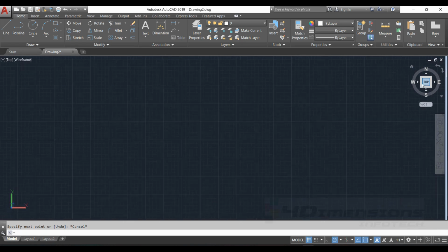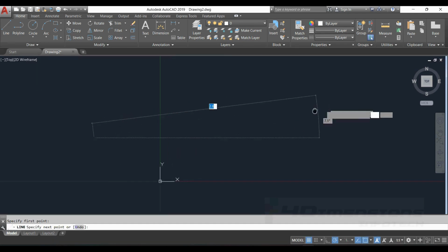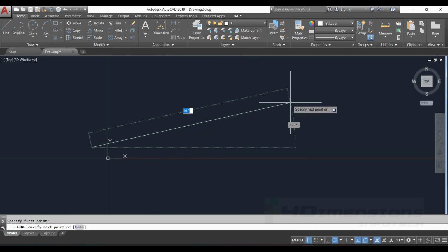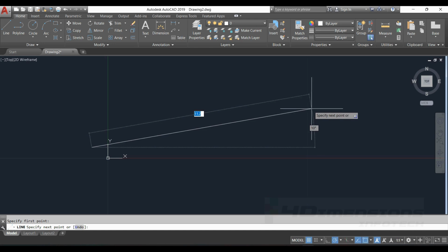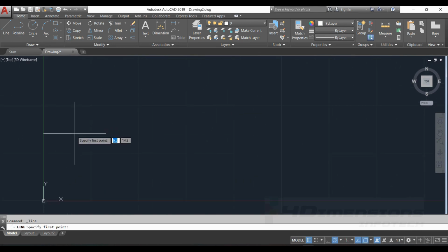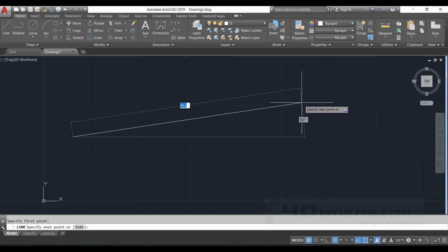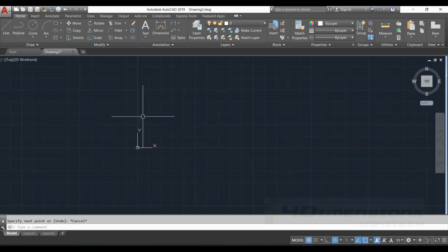After clicking, you will see the setup is adjusted automatically according to millimeters. Now if I take the line here, it is showing values in millimeters such as 10, 20. It is not coming in thousands now. Still, if I want to scale it more, I can scroll here, and now we'll take the line. It is showing the length now in 40s and 50s. This green and red line, the intersection of both lines, is nothing but the origin for this page, having the UCS at the corner.